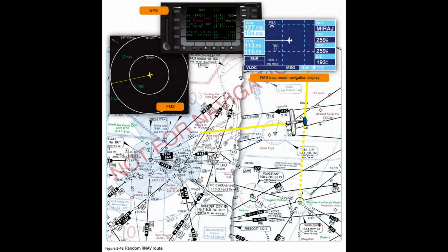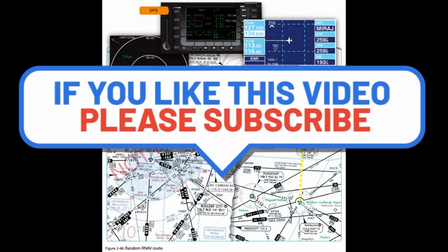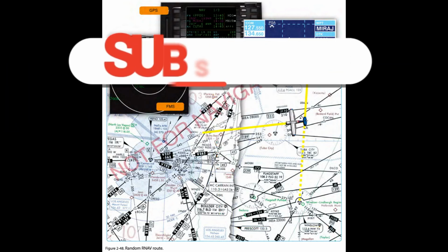Denver Center comes back with the following amended flight plan and initial clearance into Las Vegas. Marathon 564, turn right heading 260, descend and maintain 16,000, cleared present position direct MIRAGE. The latitude and longitude coordinates of the aircraft's present position on the high-altitude chart is N36°19.10 and W110°40.24 as the course is changed.